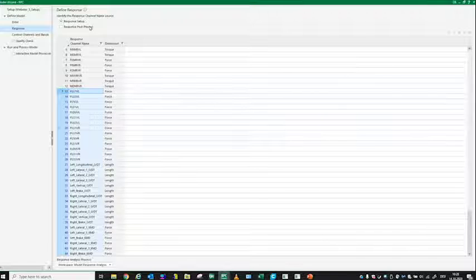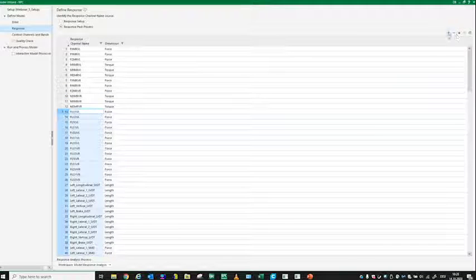You just go here, say response post process, and once you've selected that one, you go here and then with the help of minus, plus, whatever is in your mind, you can just, in my case, remove these channels here. And what happens is RPC will resort it, saying, okay, these are the only channels I'm interested in. And then in the interactive model processor, oh, I didn't hit that button, sorry. Now I hit it. So RPC is loading.